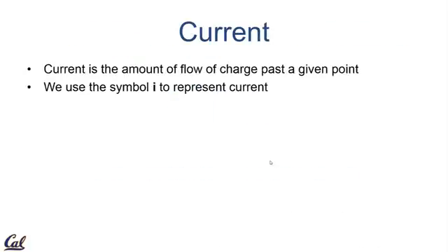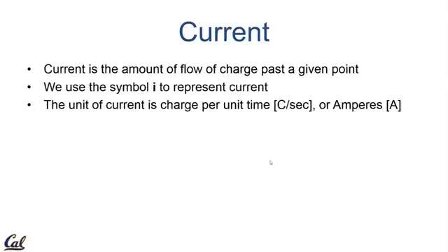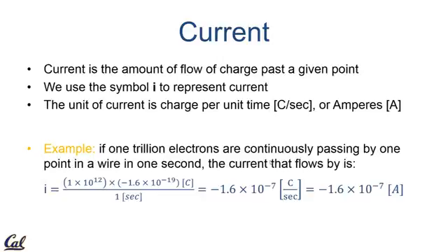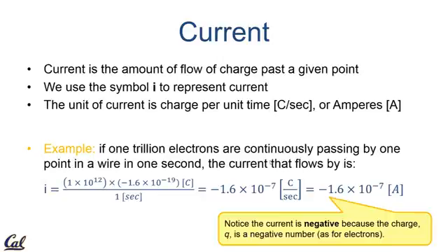What about current? We hear the term current. What are the units of current? Yeah, the unit of current is actually coulombs per second. It's the amount of charge that flows through your wire in a given amount of time. Perfect. And for those of you that have a little bit more math, there's a nice differential way to express that. If you know a formula for Q, the charge, then the current would be the derivative of charge with respect to time, or dQ/dt. So I equals dQ/dt.